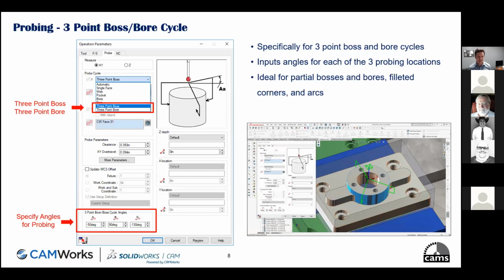And then obviously, if we have multiple entries, you could define ranges in your TechDB for drill parameters for any size between like 0 and 1 inch. And as you all know, there's a lot of drill sizes between that. You just use a percentage of diameter, and that'll help you control your peck value. So it's not one static peck amount for your .25 diameter drill that is also used for a 5/8 diameter drill. It'll help adjust that right on the fly. Yep, that's one of the enhancements. It's really been a popular request from a lot of our customer bases. Great. Thank you, Brian.